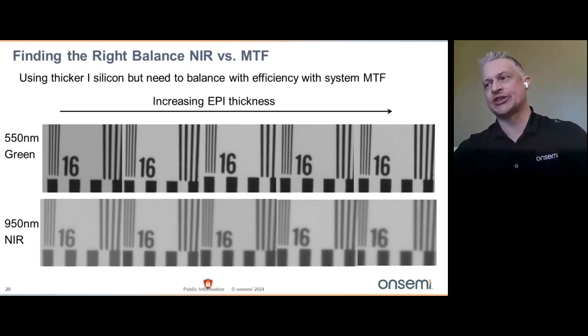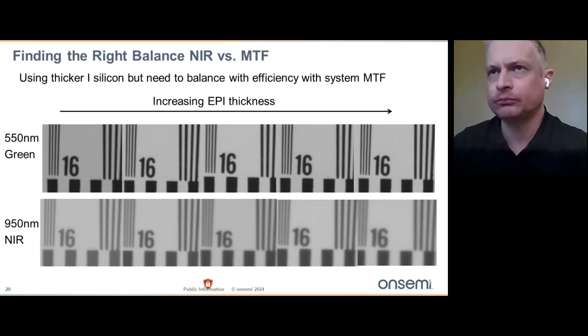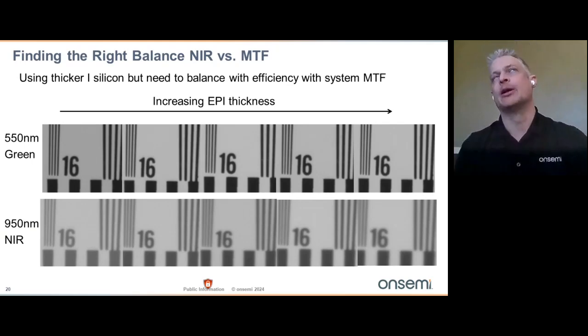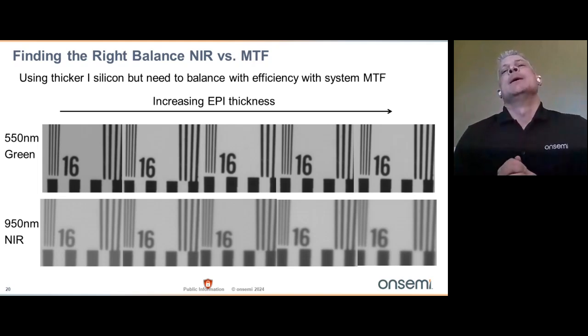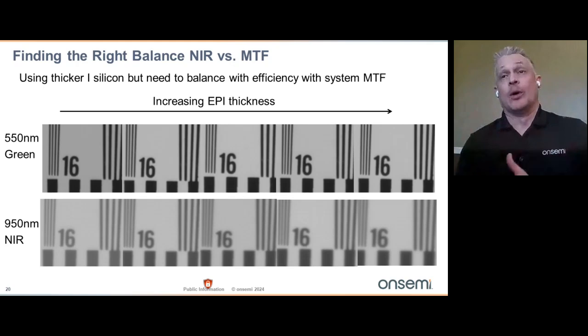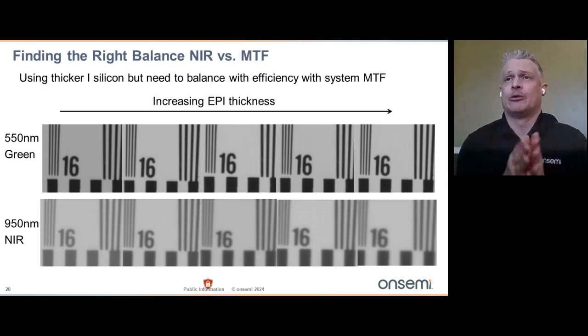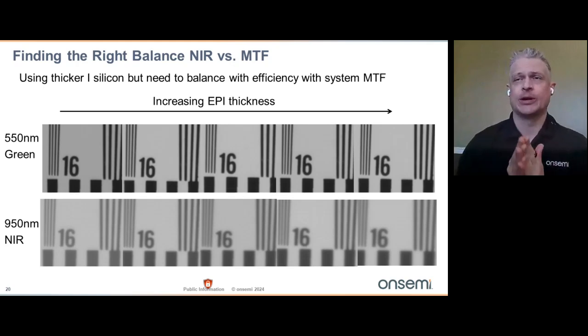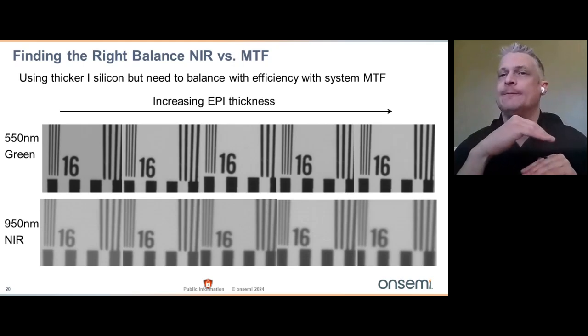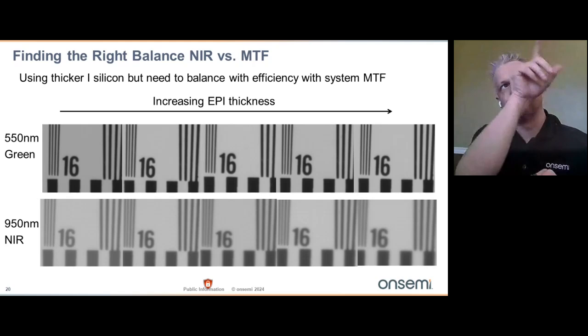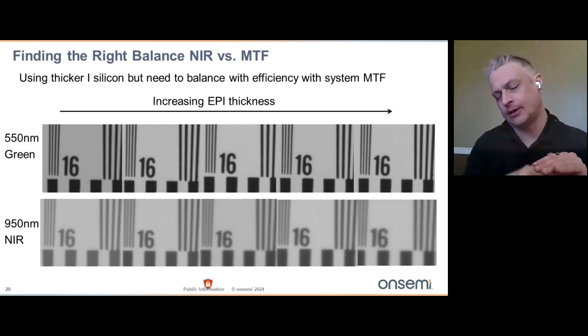Now, also going hand in hand with that, I mentioned the key case for global shutter is the active lighting or near infrared lighting. One of the ways that we can improve the near infrared response of that photodiode is we can make the actual silicon that sits beneath the photodiode, we call it epi, thicker. And that means that the light can travel down through that pixel.